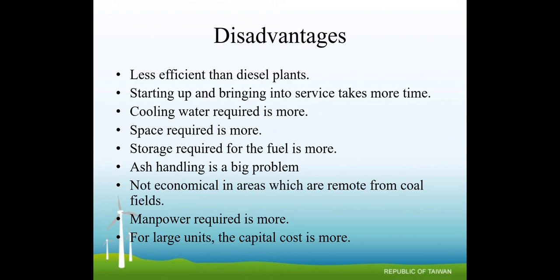It has many disadvantages. The first one is efficiency. Starting and bringing into service takes more time. Cooling water required is more, space required is more, and storage required for fuel is more. Ash handling is a big problem, which other power plants do not have.